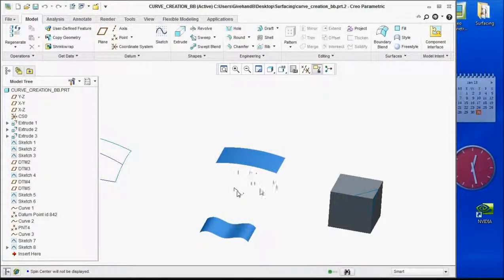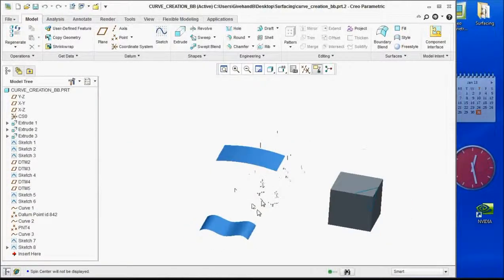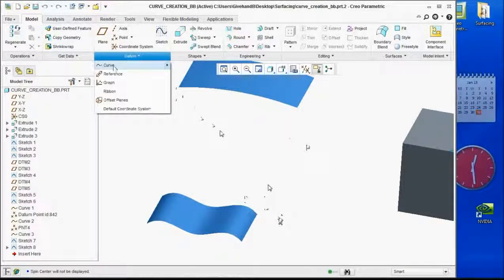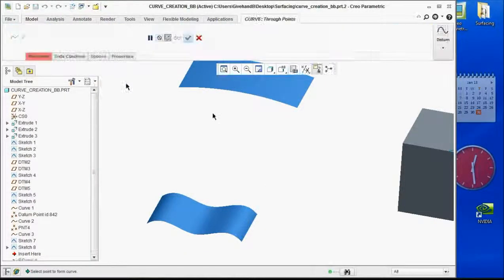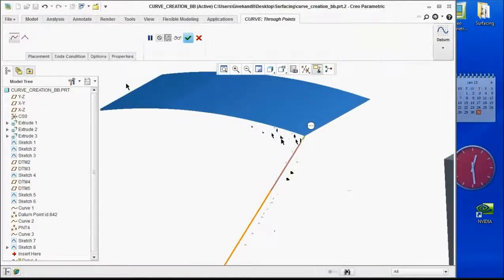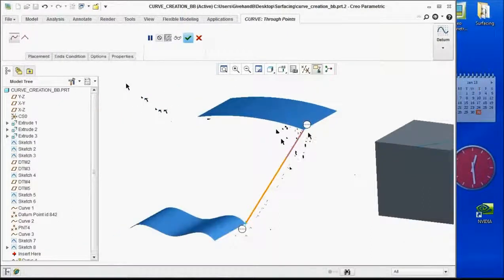You also can make your own curves to control outside shape. Now, this is creating my own definition of what this side curvature and also shape of this surface should be. And I can do that through coming in and saying I want to create my own curve. Okay, it's called curve through points. Now, if I pick curve through points, I'm going to pick this point and that point, and by default, what will give me here is a point, or essentially is a straight line.